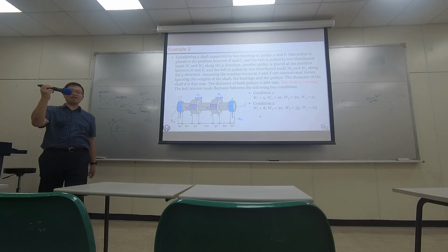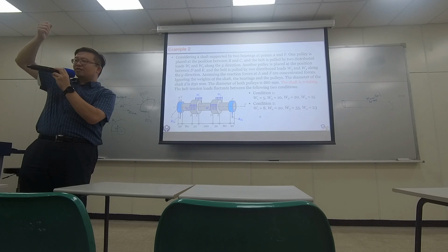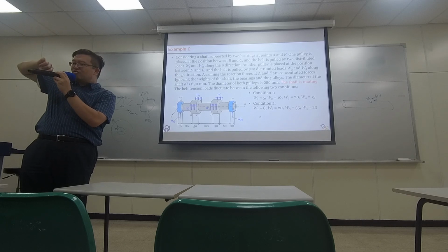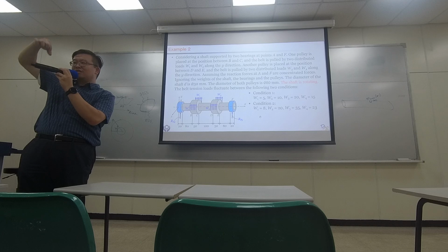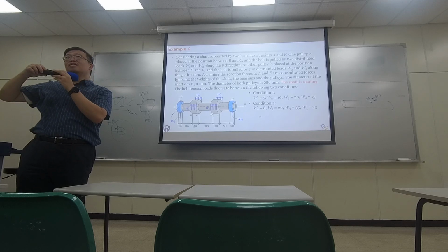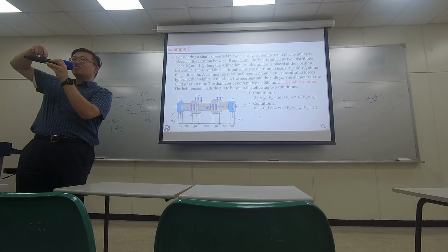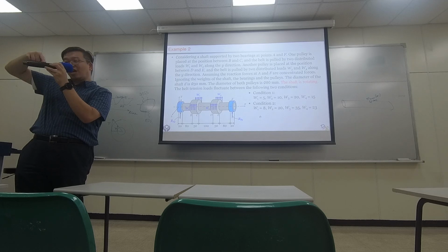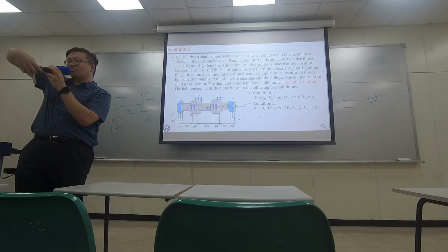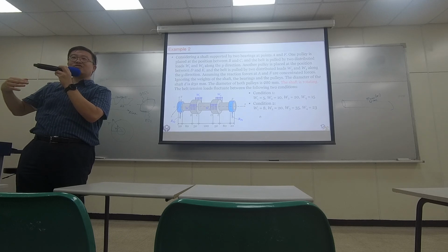Let's say this is a shaft, and I already have a fluctuating belt force, but I'm also rotating. That means somewhere at the top of the shaft could be carrying compression, but when it rotates to the bottom, it's being pulled, having a tensile condition.